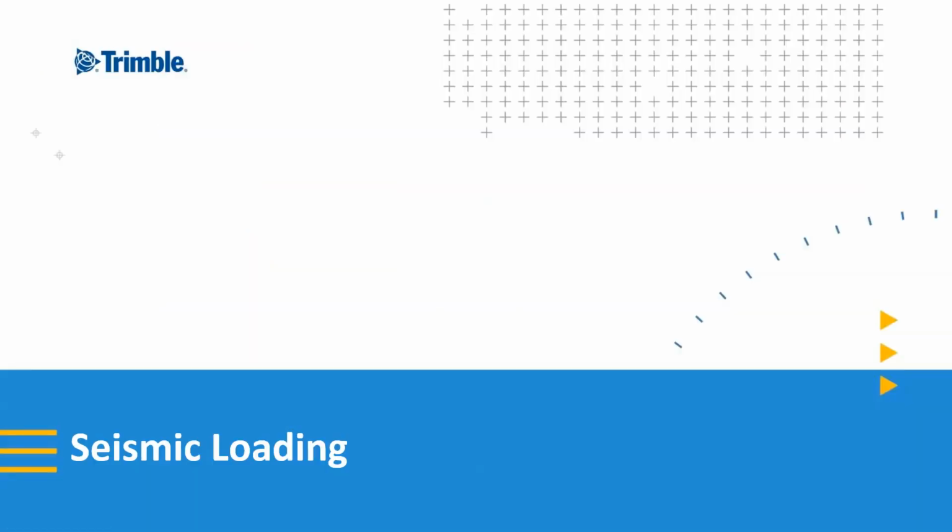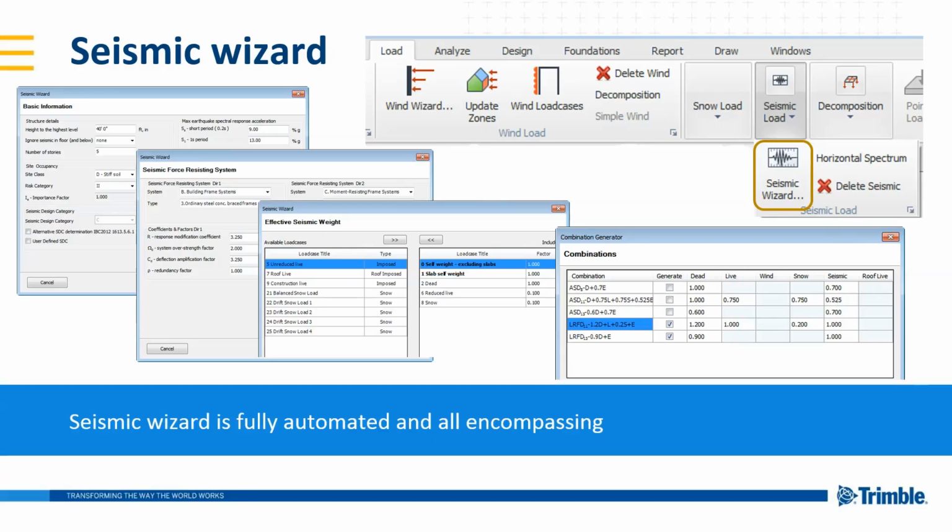Lastly, let's talk about seismic loading. And we'll see that the seismic loading is the most automated of the three, with all the steps for loading contained within the wizard. And as you're probably already expecting, we're going to start by selecting the seismic wizard from the loading toolbar, and a series of dialog boxes will walk us through the necessary information that it needs to calculate the seismic forces.